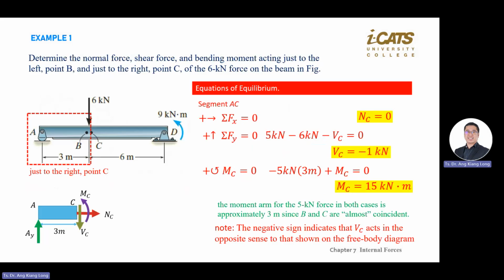Okay, again, just to summarize what we learned so far. First, when you see an internal forces question, what do you do? Solve external forces first, or solve the support first. Don't go into the detail. Look at the diagram, solve for the support, convert all the supports into forces. Then convert into a free body diagram.